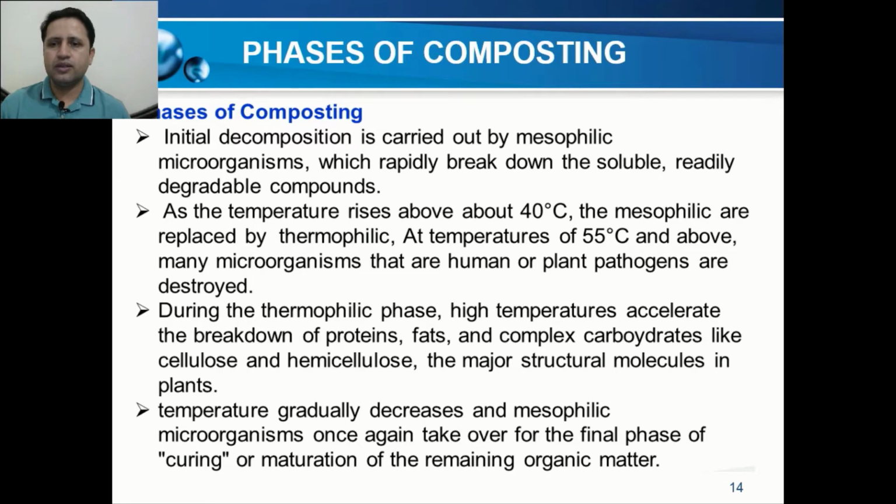During the thermophilic phase, high temperatures accelerate the breakdown of proteins, fats, and complex carbohydrates like cellulose and hemicellulose, the major structural molecules in plants. After the thermophilic phase, the temperature gradually decreases and mesophilic microorganisms again take over for the final phase of curing or maturation of the remaining organic matter.